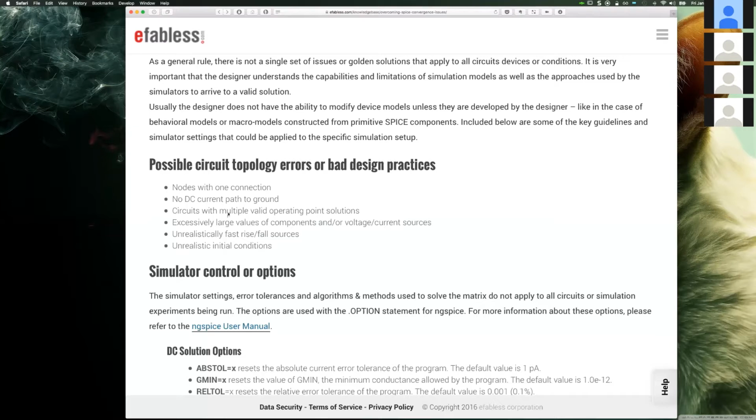Now, this is where the startup circuits come into place. In general, we are told that when you have these circuits, you know they have multiple operating points. But there's not a bulletproof answer to identify these operating points unless you act on it and treat it with judgment, interrogating or identifying points in the circuit that have this property.